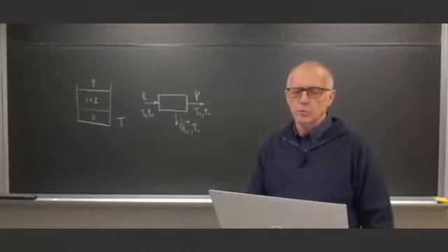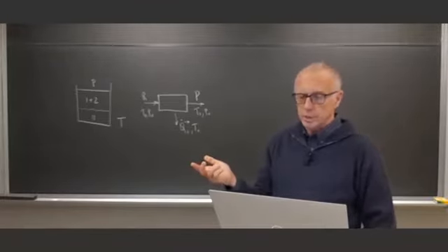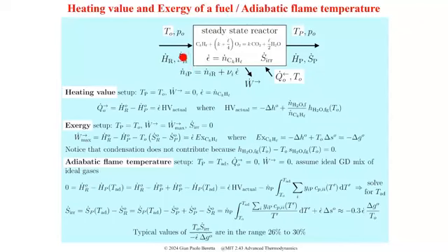Sometimes you put in your fuel pre-mixed, so you mix the fuel with the air, so you have a mixture. And in the entropy balance, you should consider the mixing terms. And then also the products of combustion are a mixture, and so you have entropy terms. So somehow these are approximations in which we are neglecting mixing entropies.